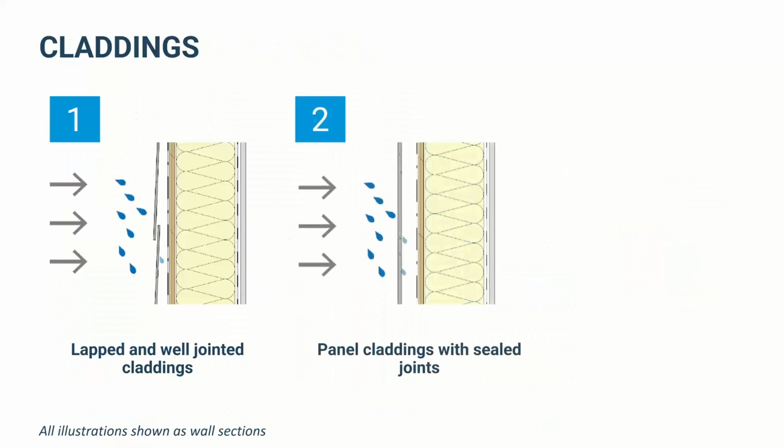So what I mean by degree of openness, right? We've got something like a lapped siding. So this could be fiber cement, could be wood shingles. Basically, almost all the water that hits this cladding is not going through. Maybe 99% is going to not go through. You might get 1% that kind of slips in around, usually around the joints, penetrations, things like that, all the window details. That's going to be where your water gets in, not really through the siding itself.